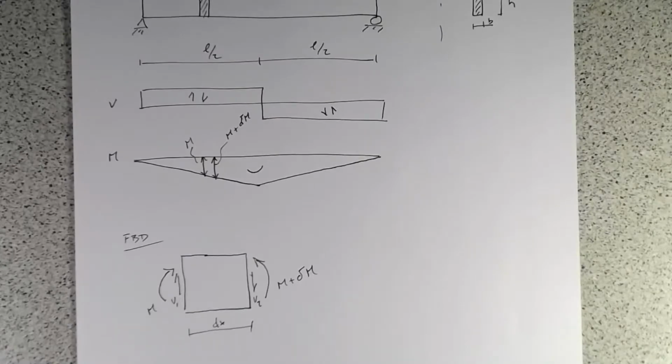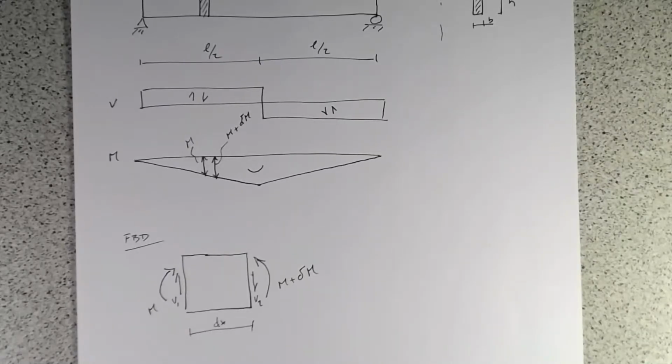We already know what our bending stress distribution is. Because we're assuming plane sections remain plane, we'll just have a linear distribution of bending stress. And like what we saw in the last video, we know that we need a longitudinal shear to resist bending stress at a given height. So we can use that and some equilibrium, and then we can work out what that distribution is.